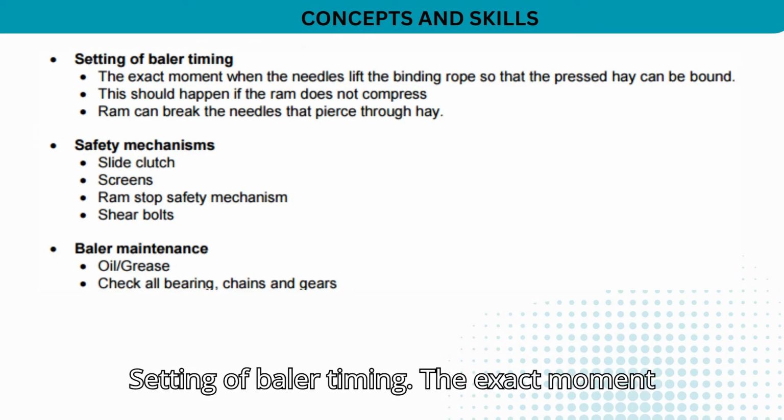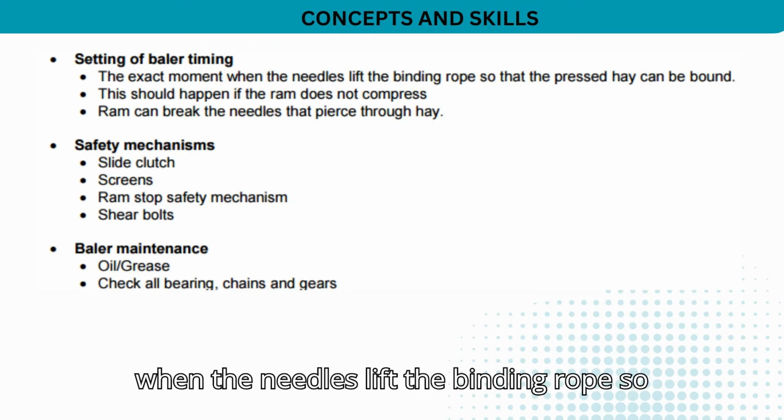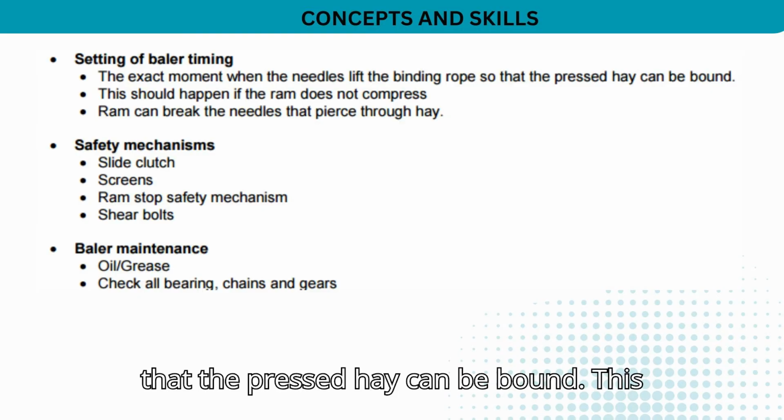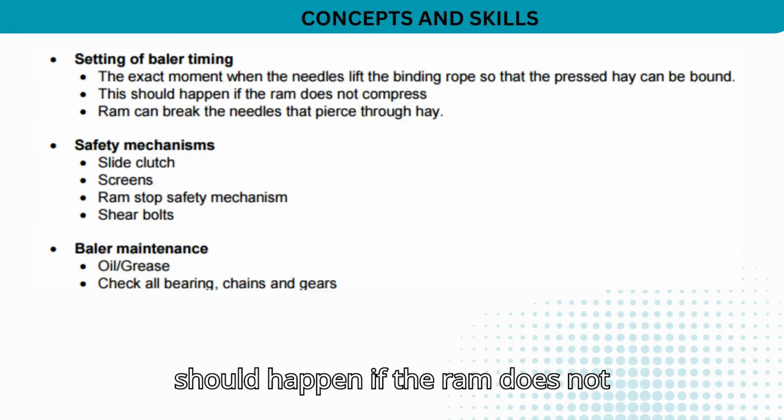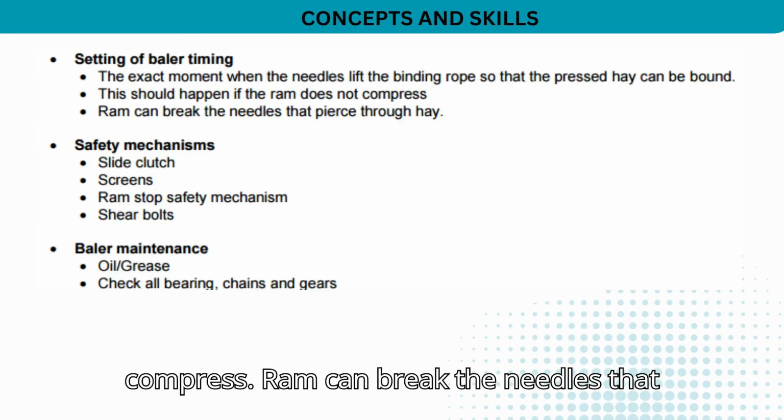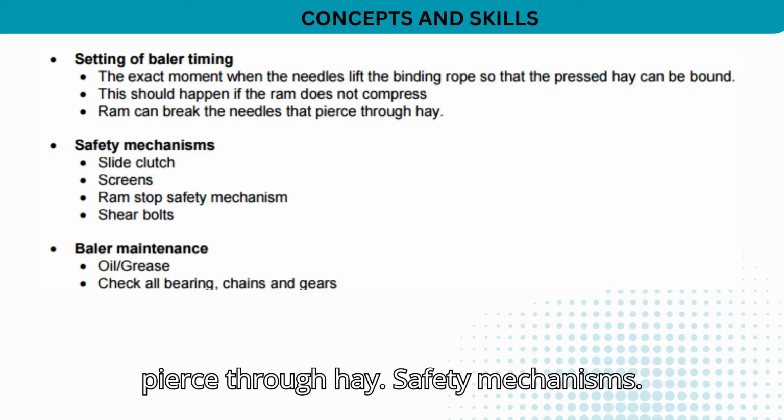Setting of baler timing. The exact moment when the needles lift the binding rope so that the pressed hay can be bound. This should happen when the ram does not compress. The ram can break the needles that pierce through the hay.